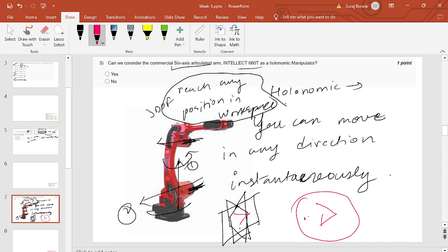Okay. So if I give this position, it can reach over there. If I give this position, it can reach over there. And this it can do in every plane, right? Because the bottommost joint is responsible for changing the plane. So if you imagine this, you will get convinced that a 3 degrees of freedom arm where the axes are arranged in this particular fashion can reach any position in its workspace.